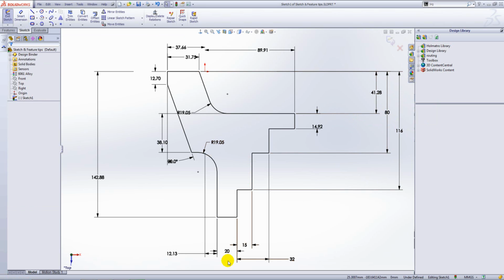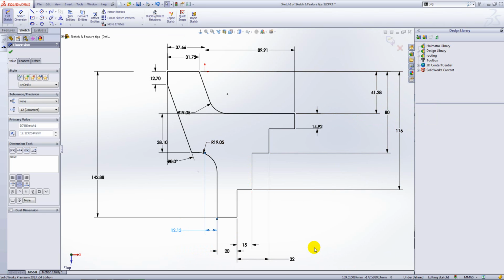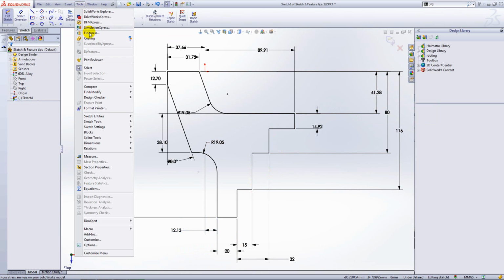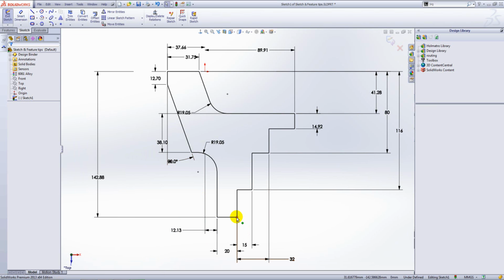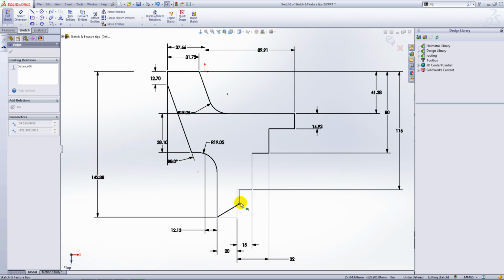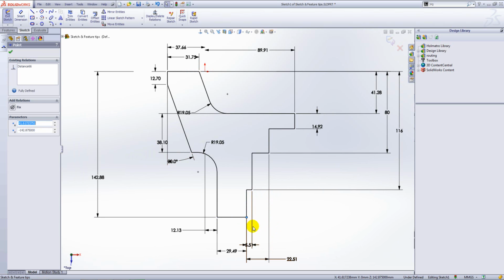Okay, now I want to adjust my sketch here, and I'm not sure exactly by how much I want to adjust it. I want to have the freedom to sort of pull it around and have a look. So to do this, I'm going to first off show you a way using this tool, override dimensions on drag move. That will just allow me to select a vertex of a line and just start to pull it around even though it has been defined already. As we release it, any updated dimensions that are referenced in that line will update to suit. We'll just undo that using Ctrl Z.